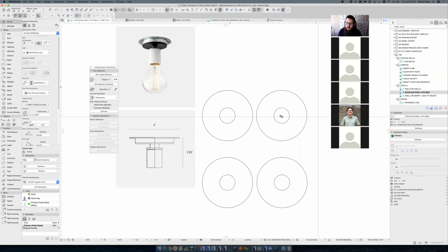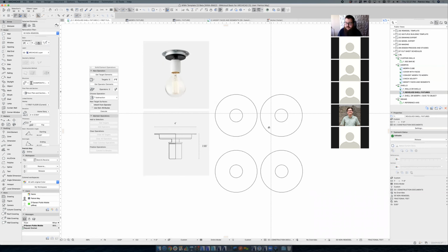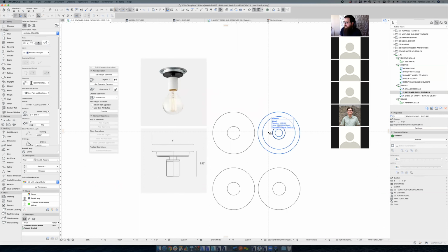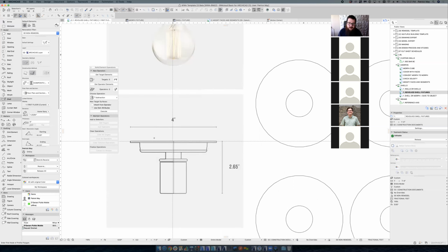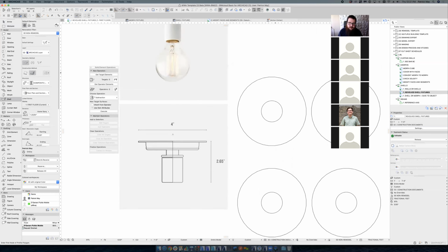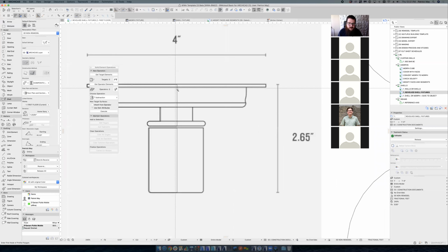Another one with the shell that I really like, and again, it's something that I use for custom light fixtures, custom plumbing fixtures and things like that, is the revolved shell. The revolved shell is basically just that. It's a revolution of a shape. I just grabbed a random light fixture cut sheet and traced it out. You use the geometry method over here, revolved, and then custom shape here. And then you can just hold down space and magic wand that.